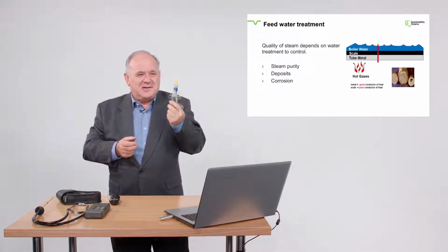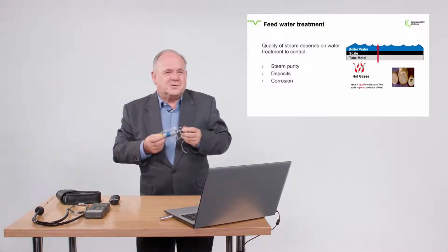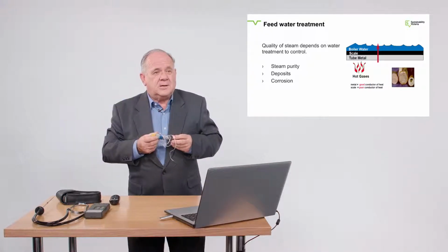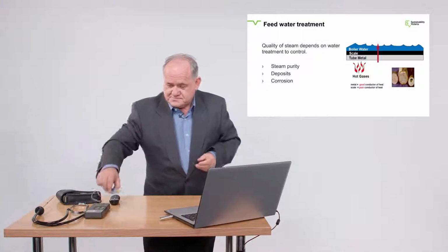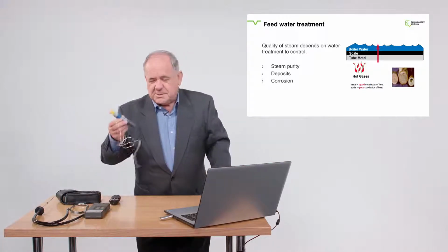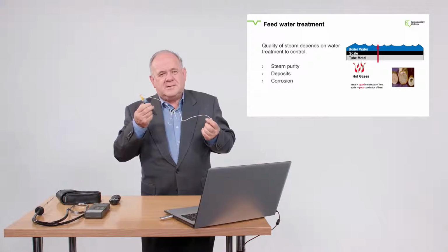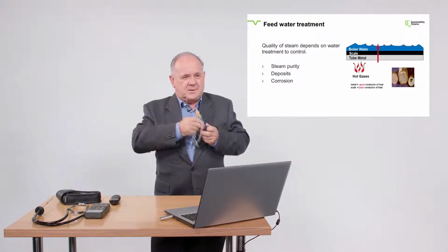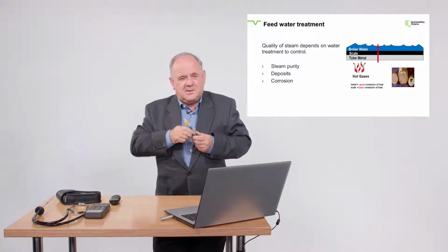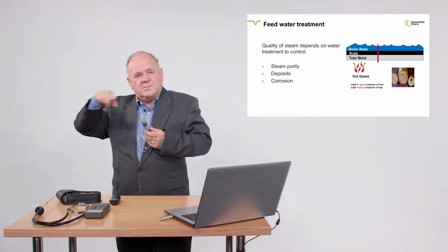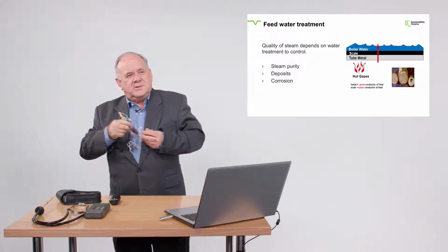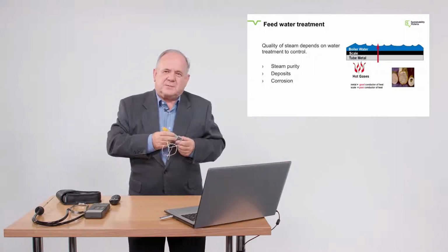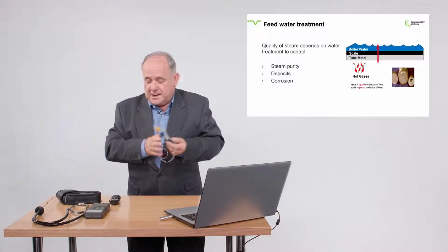So it's not a large investment when you're talking the sort of capital and the criticalness of boiler plants to just have a little logger like that available. We also use these as a temporary little gas meter because when the boiler's on high fire, it uses so much, the temperature's higher than when it's on low. So you can work out when the boiler is on high and low using just a simple little device like that, instead of having to put a gas meter on the boiler. So it's a handy little tool to have.